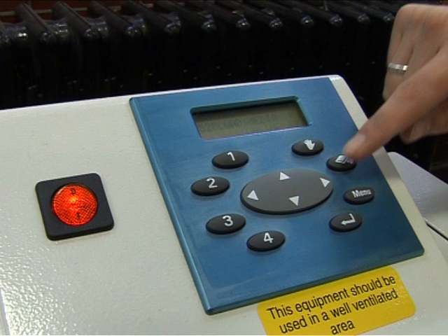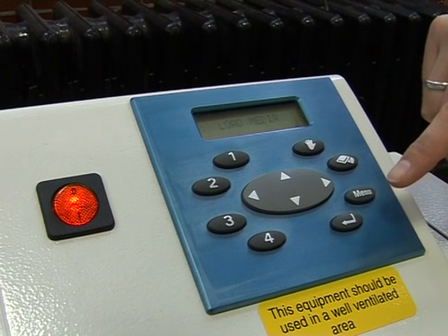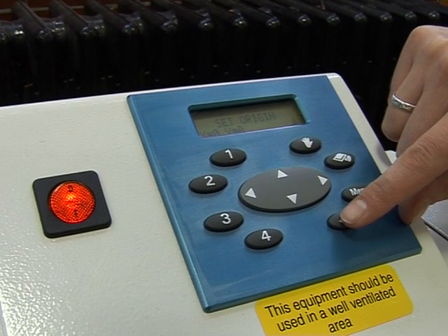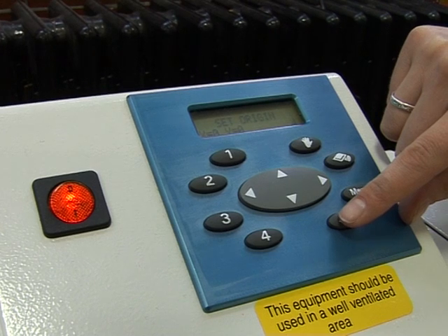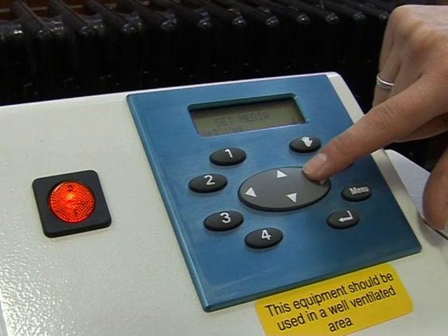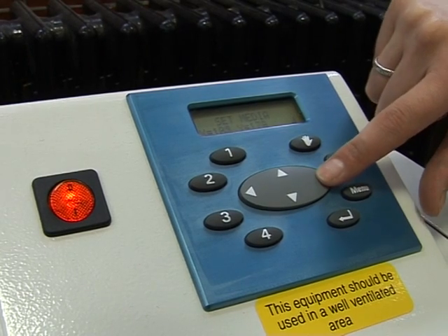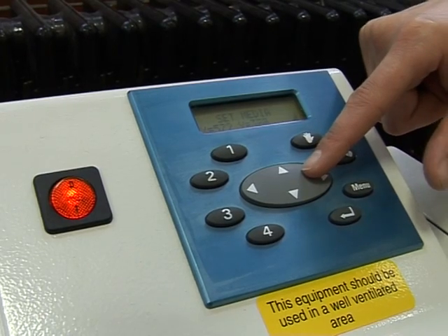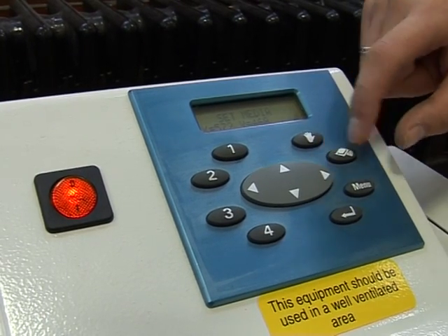Press the Media button that looks like a roll of fabric and the display will show Load Media. Press Enter. The display will now show Set Origin, but do not touch the arrow keys. It's important here to realise that you are setting the top right corner but not the bottom left. Press Enter. The display will show Set Media. And now use the arrow keys to move to the top right hand corner of the fabric. Press Enter. The laser will now travel back to the origin.